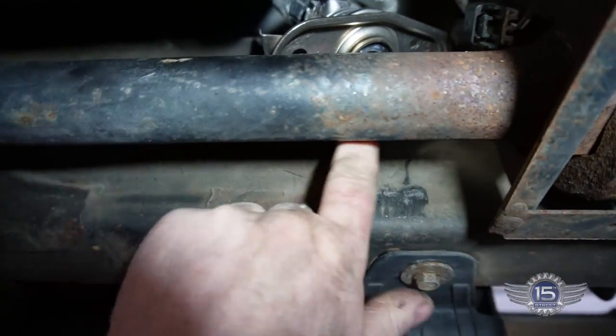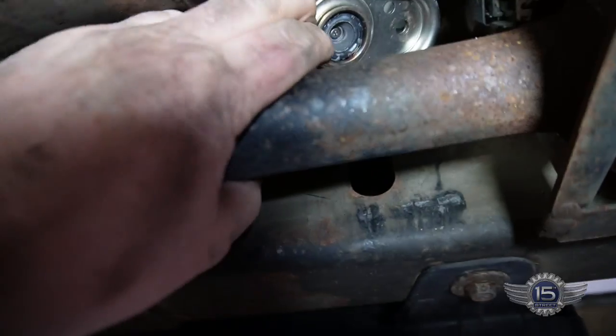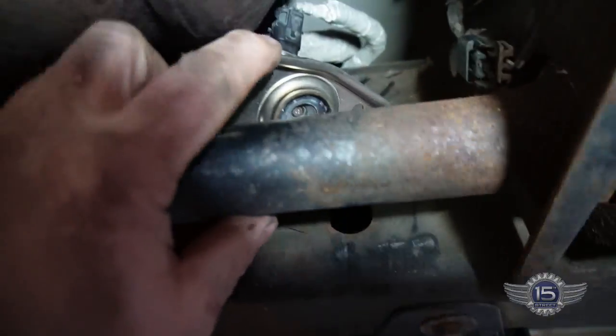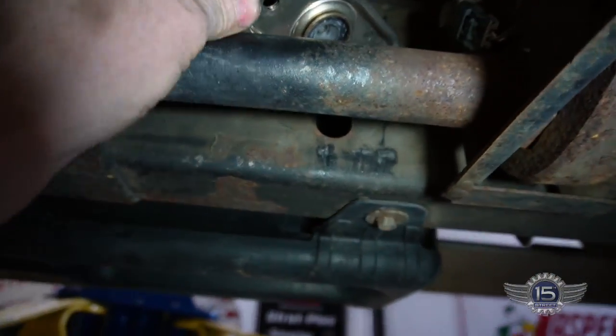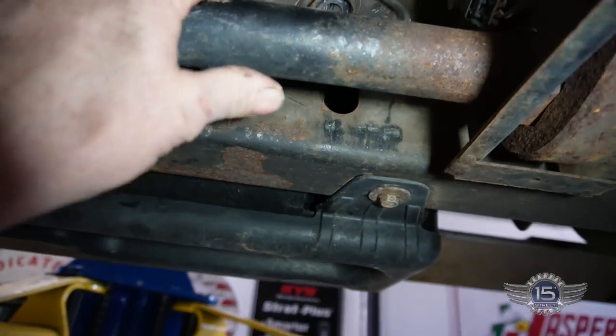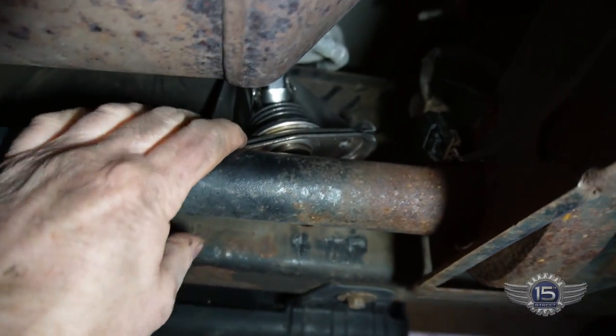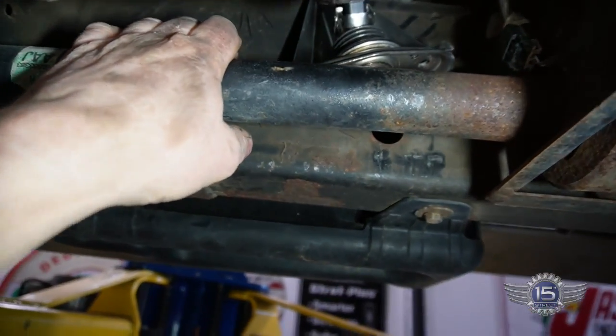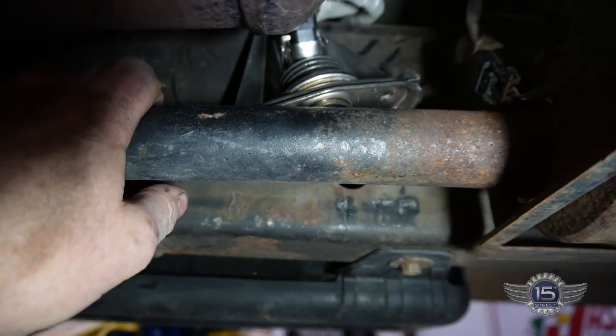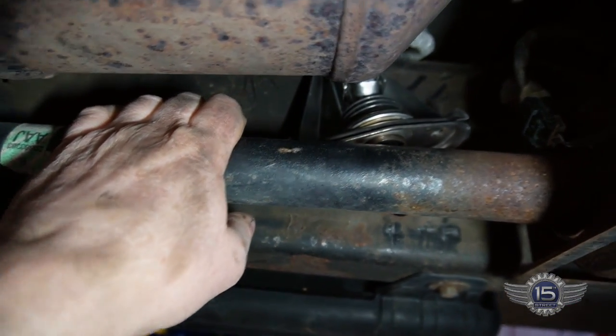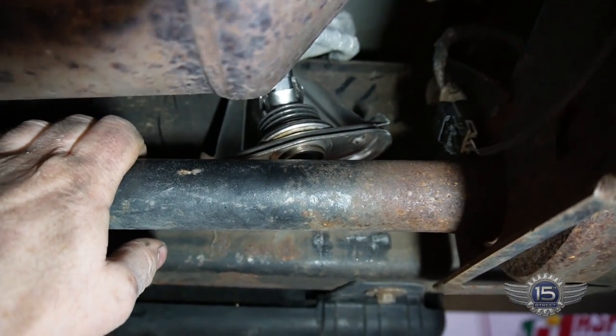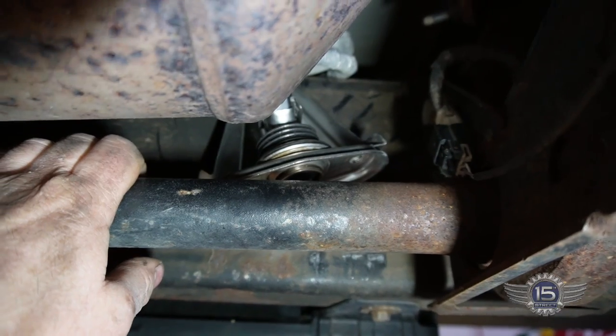It's going to spray out of this orifice right here, and it should produce about 50 milliliters in the test time. So we'll go back up and grab the scanner, turn the key on, and then we'll come back down here and put a beaker under there and let it run its test.